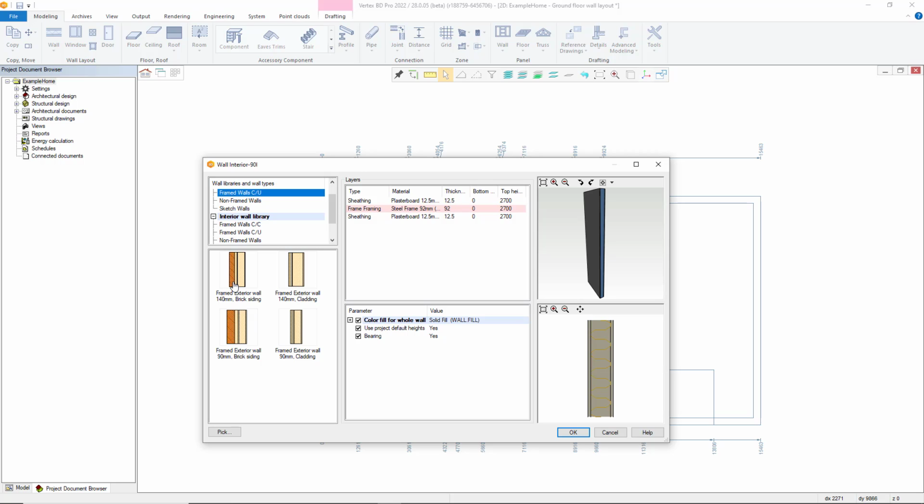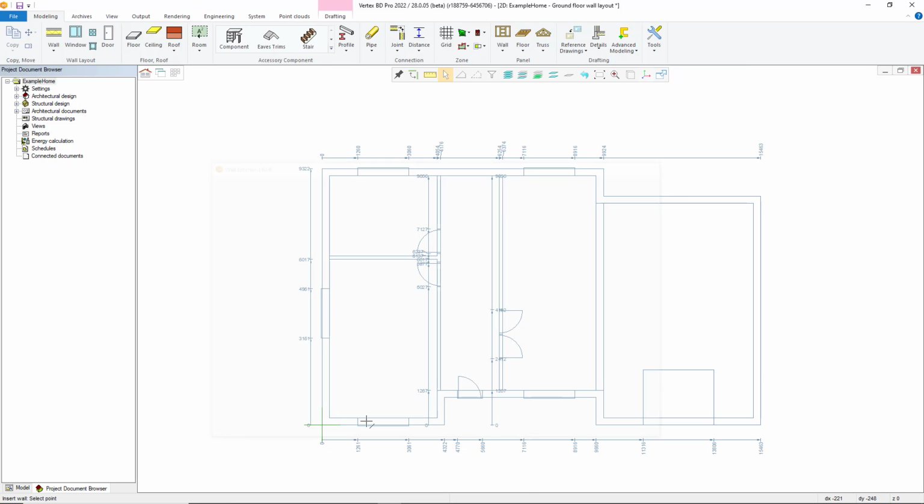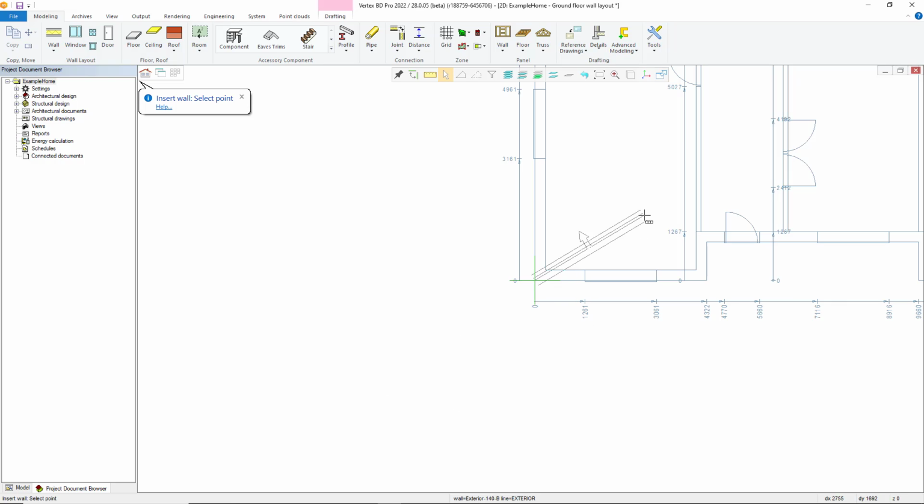First, select the starting point by hovering near the green plus sign, which is our global drawing origin. Here you'll see a little yellow snap point. Left click to select that point. You can zoom in closer by scrolling the mouse wheel if you need. You can see the wall is then attached to the origin point and the cursor.